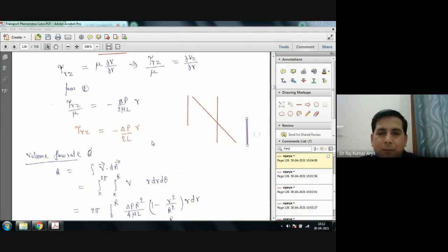And now, what would be the benefit of calculating that? Based on that, you will calculate how much force I should apply on this particular pipe to keep it on hold at this particular place. Because once you have calculated that, you can say what my clamp size or the tightening of the bolt should be, because all pipes are always clamped, they are not kept open.